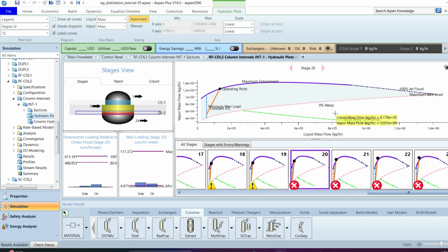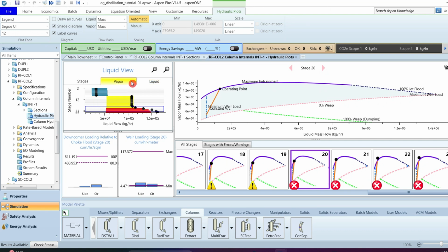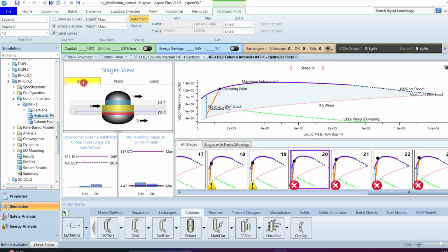Unless all the hydraulics of the column internals are ensured, and the traffic of liquid and vapors is appropriate on those column internals, the column won't be considered as an operationally feasible column. Then playing between the reflux ratio and number of stages is another task, where the number of stages gives a capital and maintenance cost, while adjusting the reflux ratio gives flexibility in the operational feasibility.